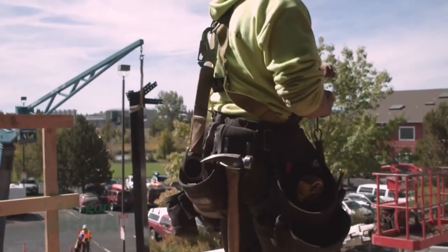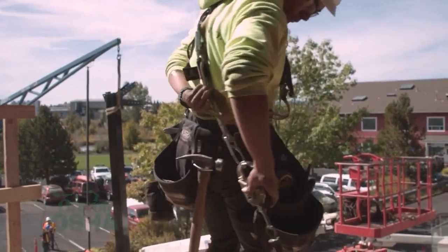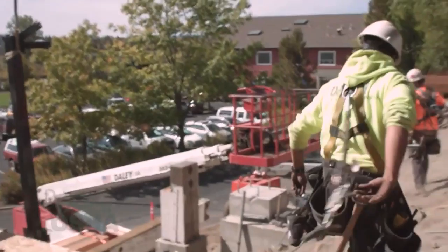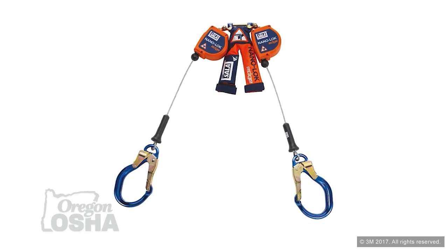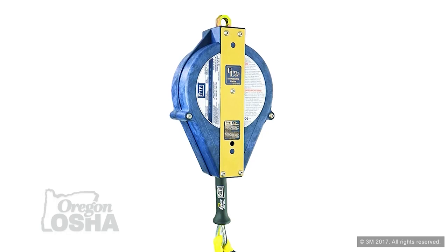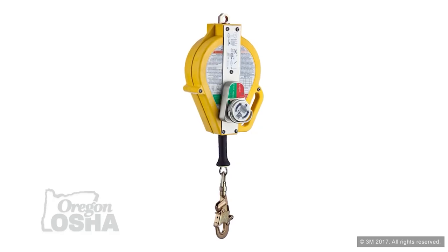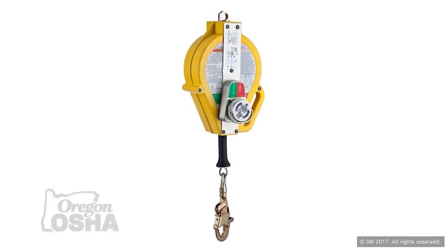An SRL is a self-retracting lifeline. Some of the common names that we'll hear are a block, a solid block, a yo-yo, which are slang terms used for a self-retracting lifeline or SRL. ANSI, with their Z359.14 standard, has broken SRLs into a few different categories, from SRL-LE, which are the leading edge devices, which may be leading edge, sharp edge devices, to SRL-R devices, which can provide rescue built right into the systems.